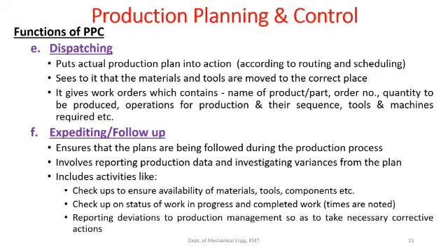All these are detailed in the work order, and this work order is what basically triggers the production operation. So even if you have a route planned, you have already established a schedule and you have already determined the kind of loading, the production only starts with the release of a work order, and the work order is what actually triggers production. So this is the fifth function of PPC called dispatching.